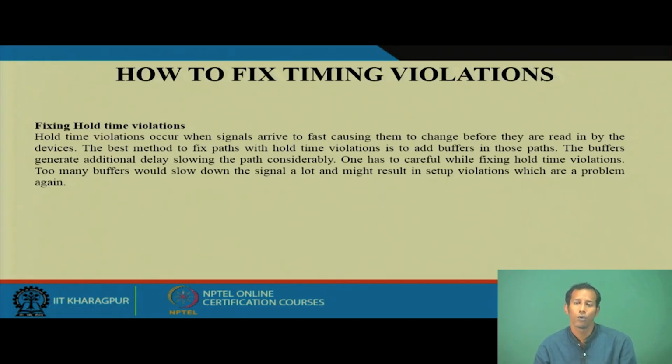So, now how can we fix the hold violation? For fixing the hold violation, first, the hold violation occurs when the data arrives too fast. We have already seen when this hold time violation can occur. But the best method to fix this path is to add buffers on the particular path, so that the data is delayed.